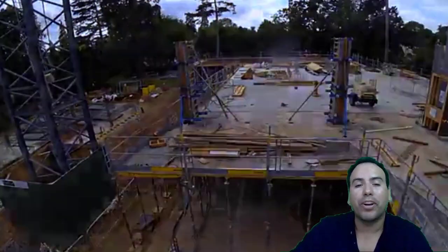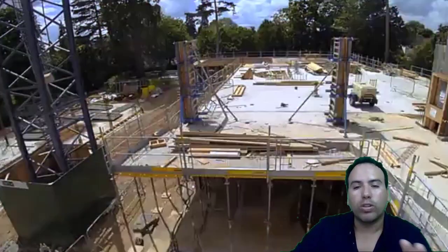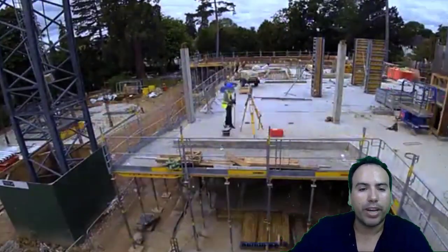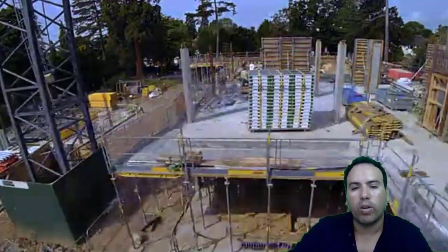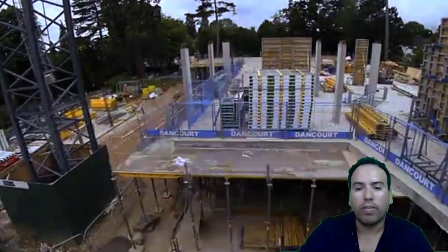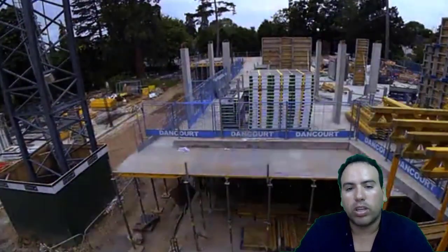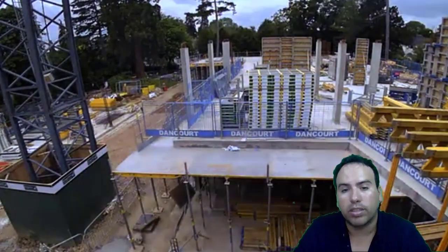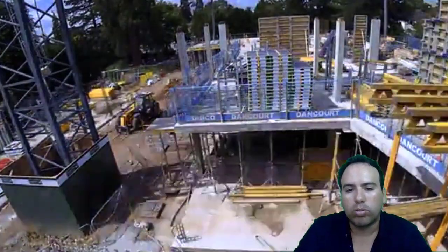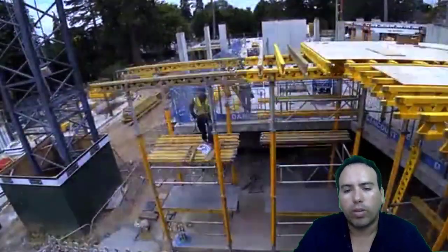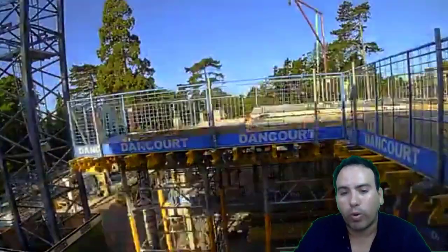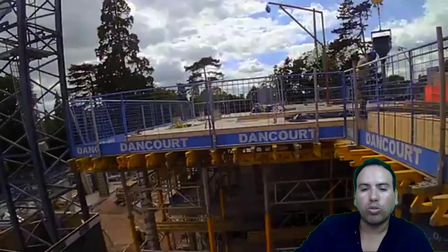So columns transfer vertical loads from a ceiling, floor, or slab, or from a beam to a floor foundation. They also carry bending moments about one or both of the cross section axes. The load on the column is the self-weight of the column multiplied by the number of floors, and also the types of loads are the self-weight, as I just said before, the loads of walls per running meter, and the total load of the slab, which includes the dead load or live load, and the self-weight. Also, the load transfer mechanism.